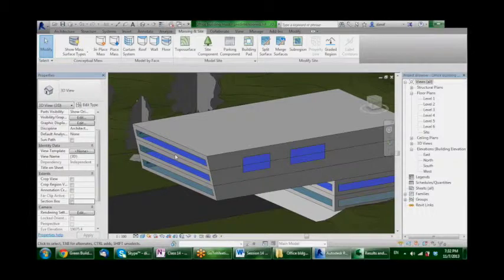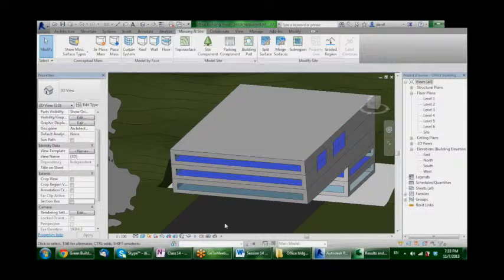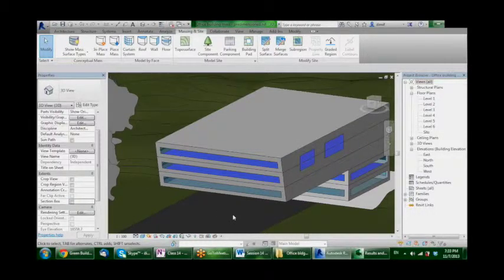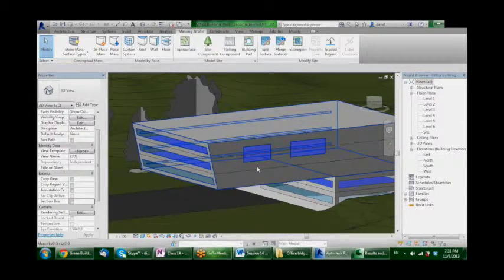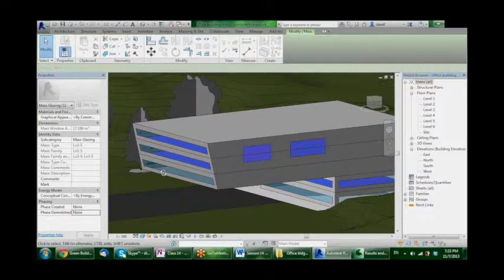I try to stick with pre-dimension glazing in Revit, and believe me, there are other tools out there like Ecotect and stuff like that that are much more flexible and allow for much more and more accurate customization. Because if you see, when I customized those windows, I wasn't able to add any dimensions to them. So the dimensioning might be a bit off, even in this model that supposedly has the same glazing as the detail model. It's not the same. This is a feeling, a ballpark about how the windows should look, but that's all there is to it.